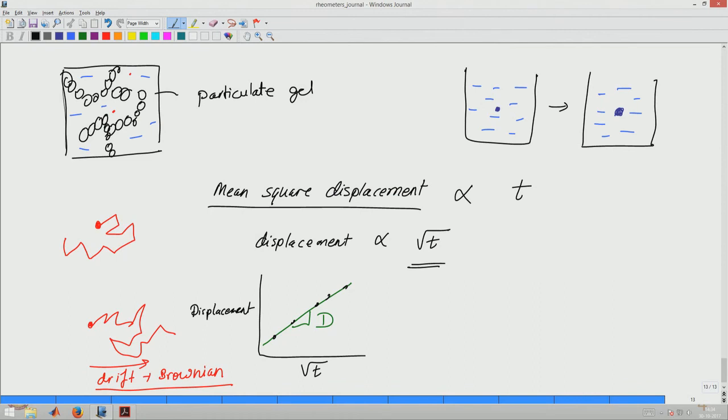Yeah. They are not affecting the fluid property. Yeah. So, what is the significance of plotting the displacement profile like that? No, using the displacement profile only you can calculate the diffusion coefficient, because when you know the displacement and you plot it as a function of square root of time, the slope of that is the diffusion coefficient, and this diffusion coefficient is related to the viscosity. What if the fluid that is surrounding these particles is viscoelastic? Okay, what would you expect?